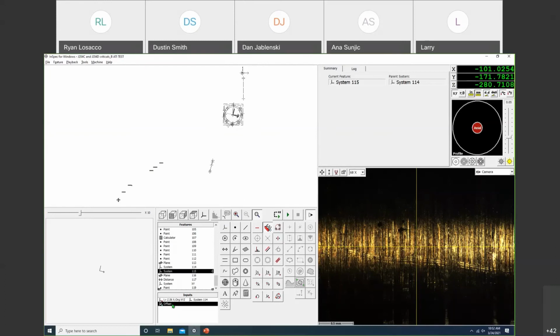I want to say this with a lot of caution, that now the machine thinks that the camera is on the side of the machine and it's angled. So any touch probe or even vision measurements, taking it in this working plane can be very, very dangerous. So if you guys have prints like this that require really 3D modification of your systems, please bring us into the loop. Let us help you out with it.